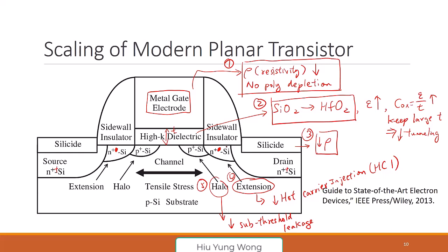You cannot pattern the aluminum first and then do the source drain, because it is going to melt the aluminum. Later, they went to silicon and then did implantation because now implantation is available. In the very early time, they could not use implantation. They used diffusion. They add a material with the dopant on top of it, heat it up so the dopant will diffuse into it.